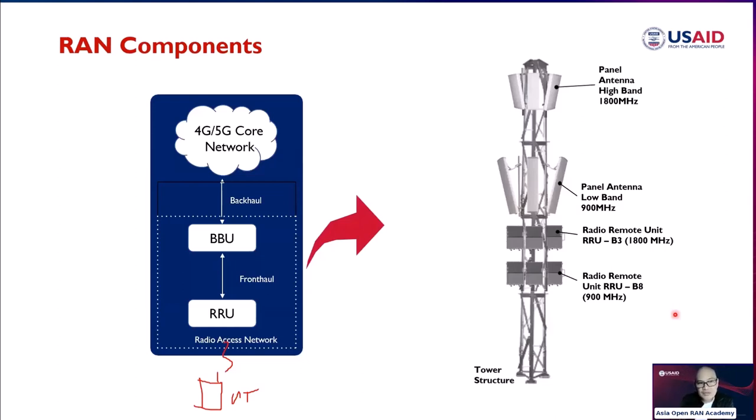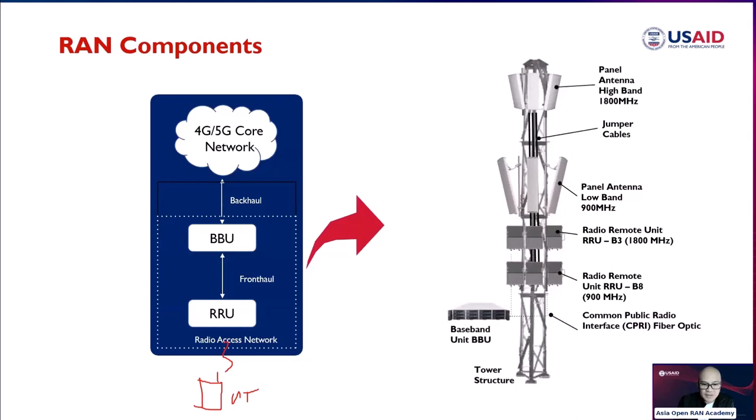If you're new to wireless telecommunications, just think of the remote radio unit as a typical radio. Here's your FM radio, and this is your AM radio. Some of the applications are the same. Now this remote radio unit is connected to the antennas via copper cable, and connected to the baseband unit by a fiber optic cable, using the Common Public Radio Interface, or CPRI.